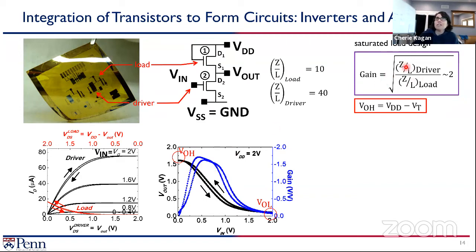The gain is related to the dimensions. It's why we picked these dimensions, so we could design a device with a gain of our selection. So as I look at this, this is where the device gain will tell you that we're amplifying a signal. So that's how we use it as an amplifier. And then otherwise, in these other voltage regions, we can use it as a switch.